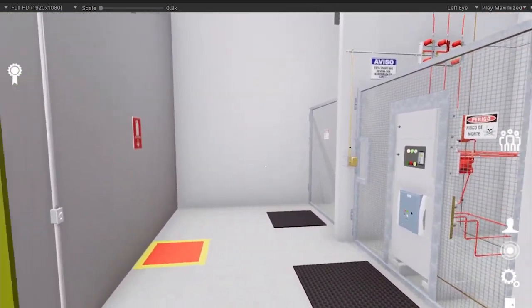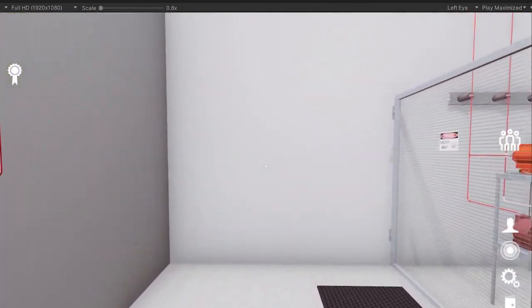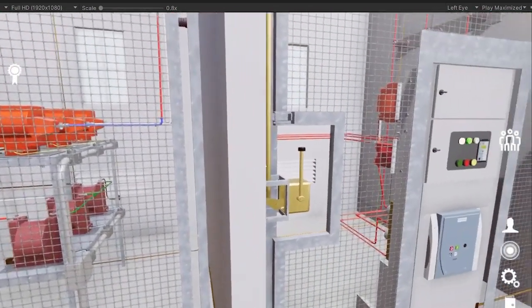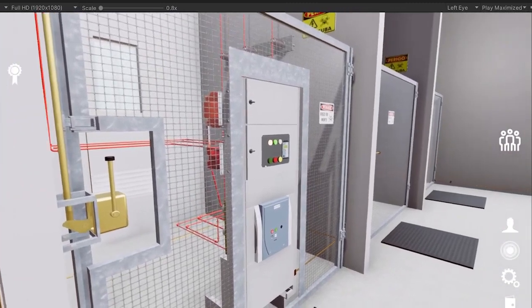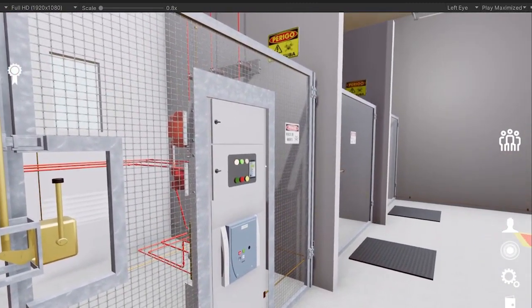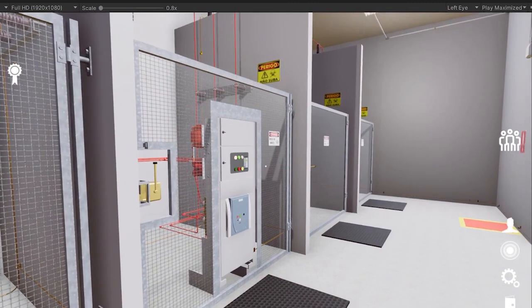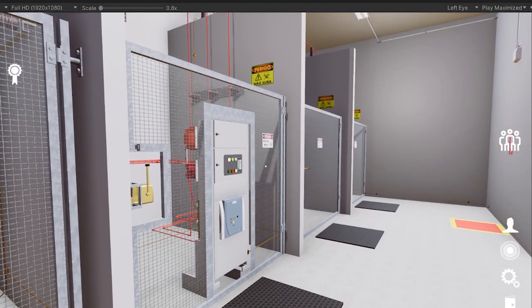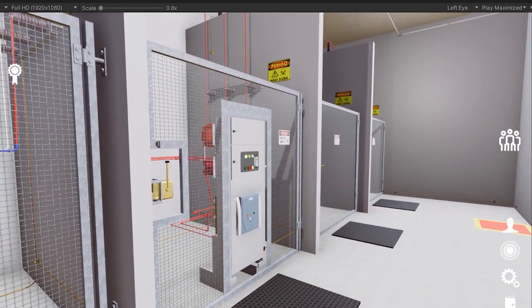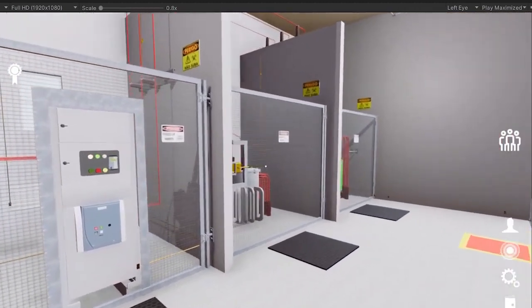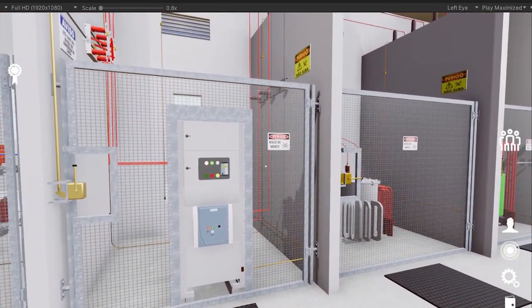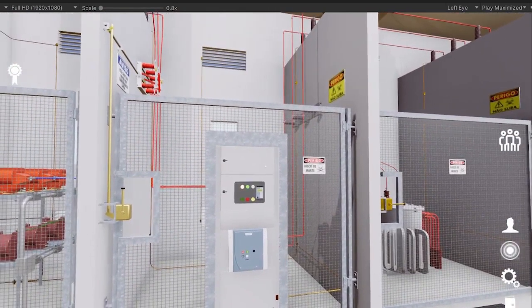Well, folks, this is the primary substation. Here we have the CTs and PTs. Anyway, everything needed to give a lesson about the primary substation. And contingency simulations like the one I did here. I can create simulations saying, look, I lost the capacitor banks, the circuit breaker protection was triggered, or this transformer here caught fire and I have to switch the power source. Anyway, the simulations will be carried out strictly according to the specific needs and requirements of the client.